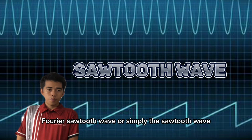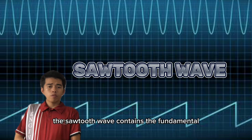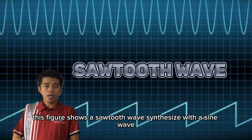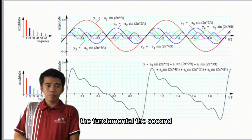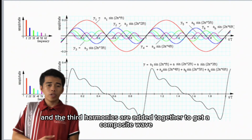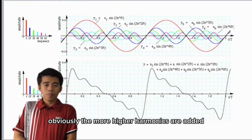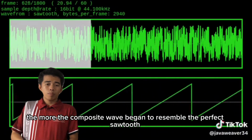Fourier sawtooth wave, or simply the sawtooth wave. The sawtooth wave contains the fundamental plus all the odd and even harmonics. This figure shows a sawtooth wave synthesized with sine waves. The fundamental, the second, and the third harmonics are added together to get a composite wave that begins to resemble a perfect sawtooth. Obviously, the more higher harmonics are added, the more the composite wave begins to resemble a perfect sawtooth.